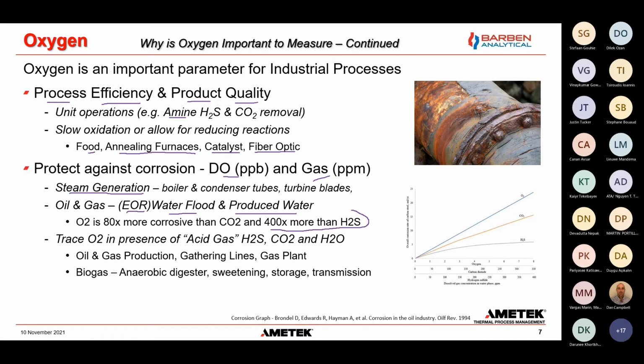It shows that oxygen is 80 times more corrosive than CO2 and 400 times more corrosive than H2S in water flood and produced water applications. So this is saltwater stuff inside downhole tubes, produced water, and water flood piping.